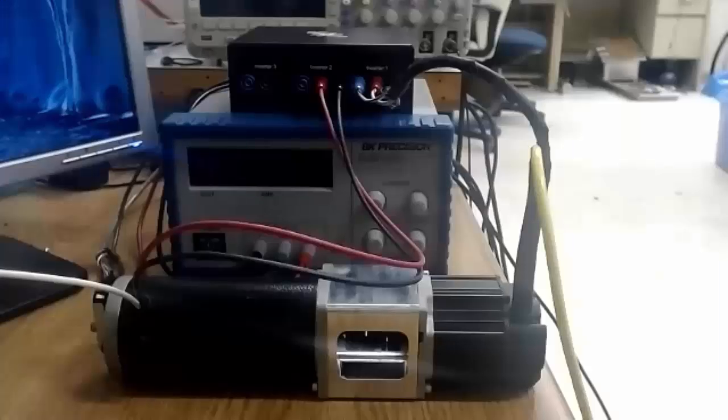Here's the view of the setup that we are going to be using for this example. All of it is exactly the same as the setup that we used for the DC motor speed control as well as the induction motor vector control experiment, except for the motor on the right, which is a permanent magnet synchronous motor. The motor is rated for 7.1 ampere continuous and a rated speed of up to 6000 RPM.